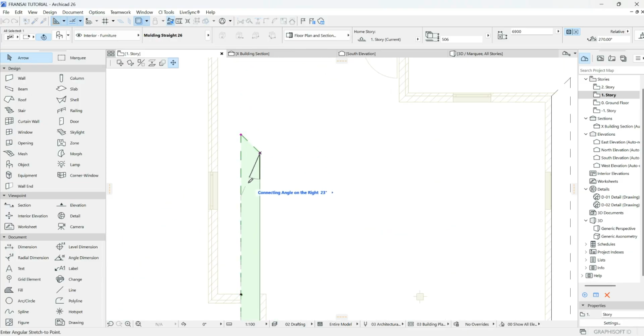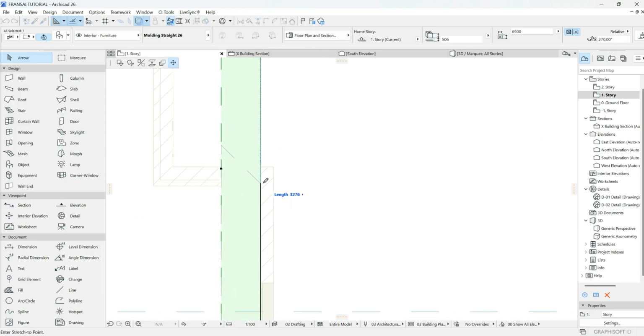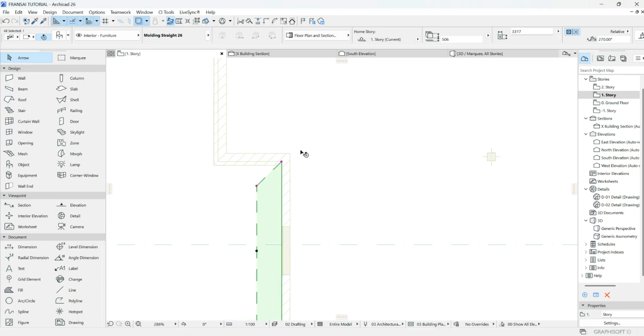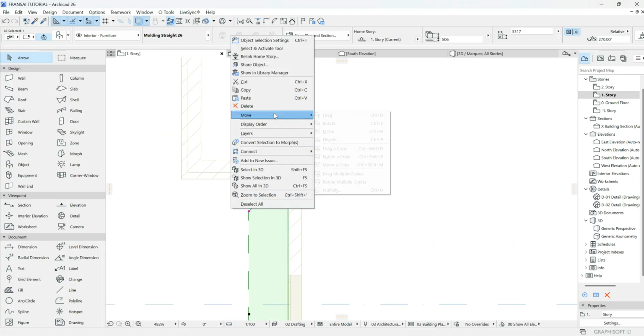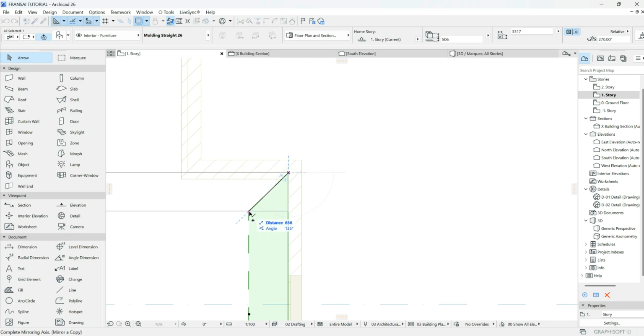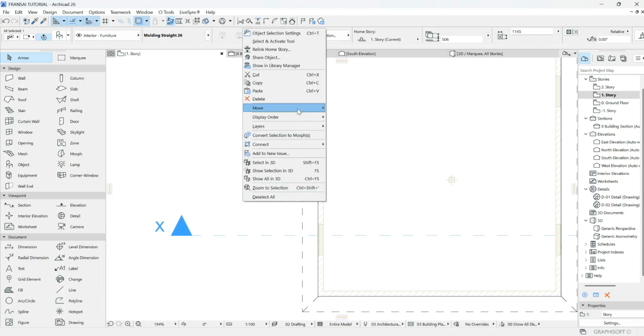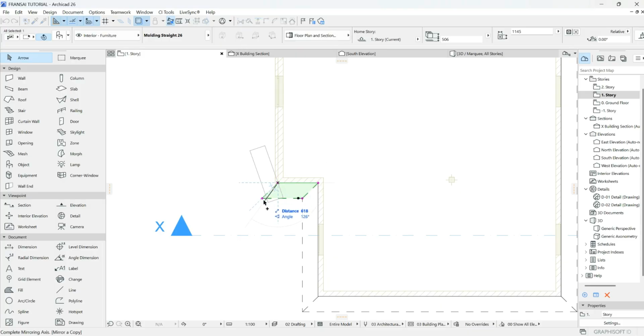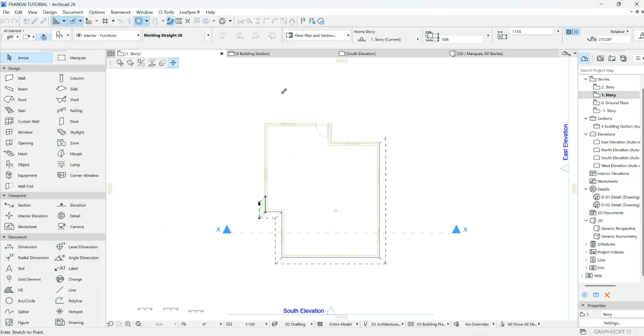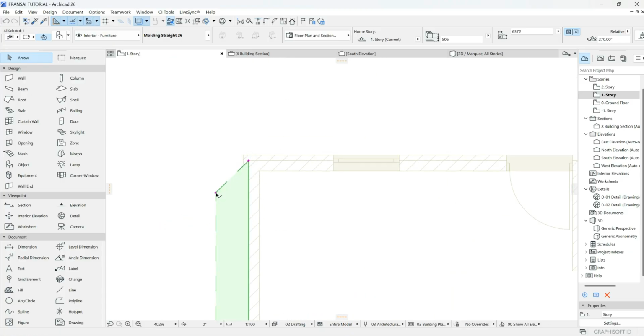If you drag this one, it will only change the angle. Yes, it will only change the angle, but this one can change the length, not the angle. Only the length it will just change, and I will equally change the angle, and I will mirror it. My mirror is, remember the mirror a copy, pick it from this point and click on this point. So I will reduce the length. I want it to end here. So I will mirror, pick it from this point and place it on this point. So I will take it to the end and I will change the angle to this.